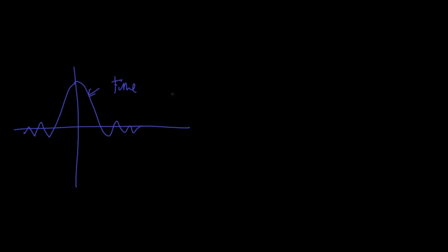Now remember, we are in the time domain, so if I draw our impulse response that is windowed, this is in the time domain, and this is not acceptable for a computer. A computer will not accept the time domain. It will only accept it in samples. So to do that, we just sample this wave. That is n equals 0, n equals 1, 2, 3, 4, and then it also goes the other way around too. So -1, -2, -3. And that is how a computer gets its FIR filter coefficients.